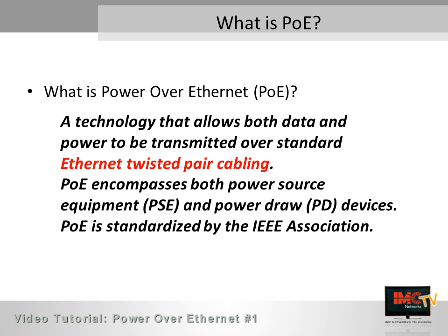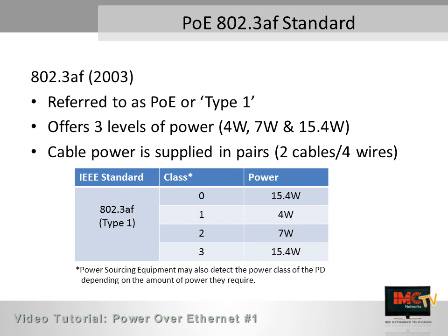So what is PoE, or Power over Ethernet? It's a technology that allows both data and power to be transmitted over standard Ethernet twisted pair cabling. PoE encompasses both power source equipment, referred to as PSE, and power draw, PD, devices. PoE is standardized by the IEEE Association. The IEEE standard of 802.3af was ratified in 2003.